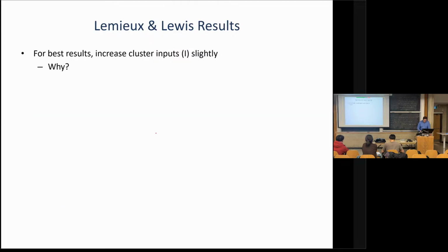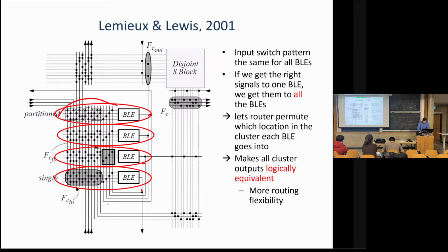Okay, so what were their results? They found that for best results, they reduce the amount of muxing inside the logic block. And they found that they should actually increase the number of inputs. This is how many inputs are coming into my cluster.